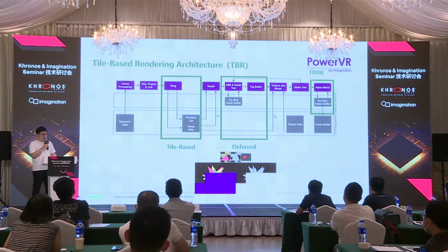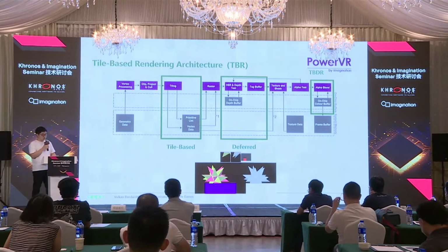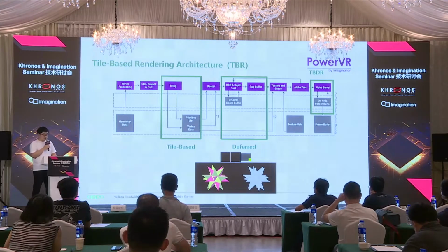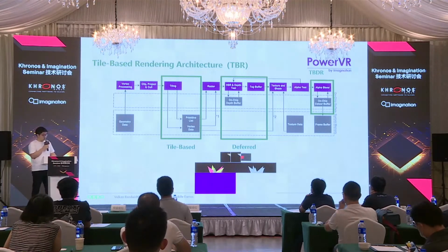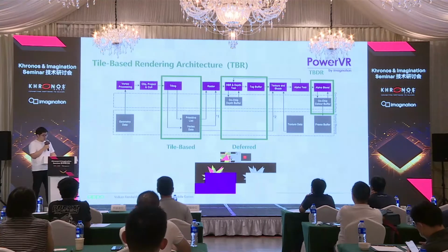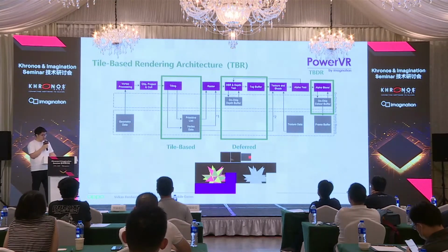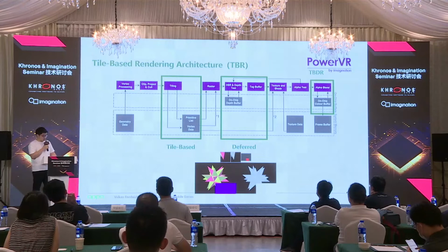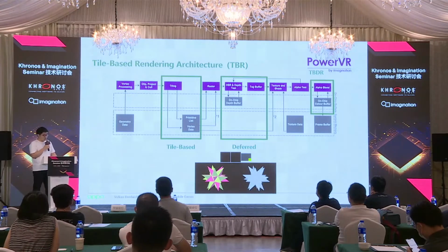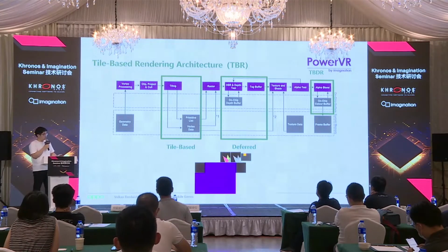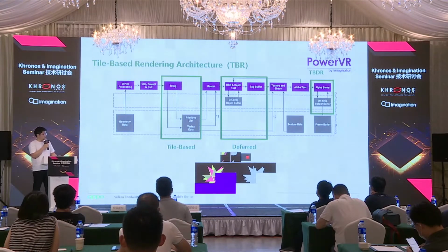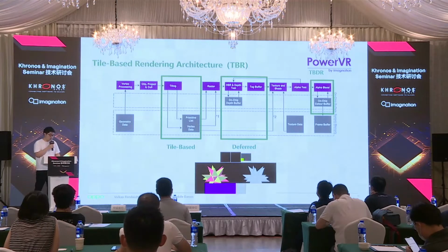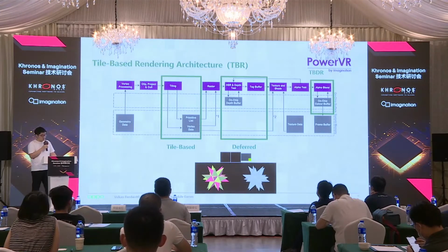They have on-chip memory for the GPU. The feature of on-chip memory is that, compared to direct interaction with memory, the overhead of the GPU reading and writing it is negligible. And tile-based rendering splits the frame buffer into different tiles. Before finishing the drawing of each tile, the GPU just reads and writes the on-chip memory. When the tile is fully rendered, the on-chip memory content will get written into the memory all at once. So that GIF describes the process.